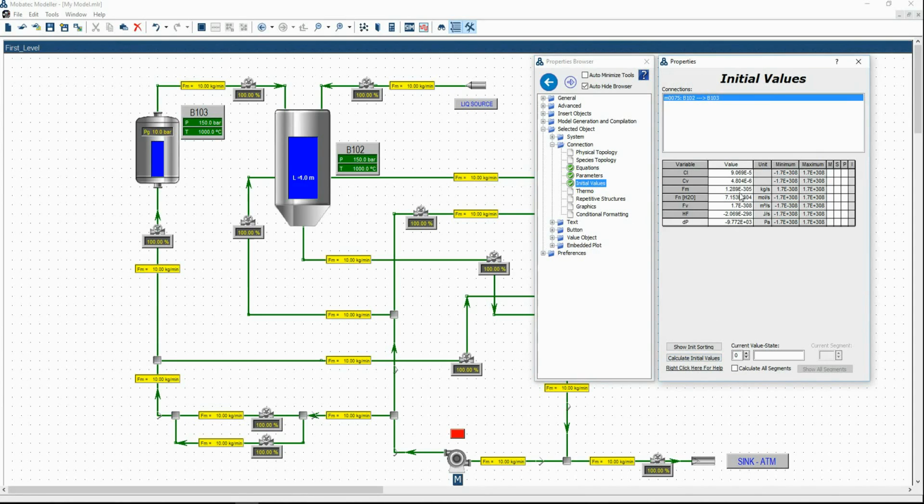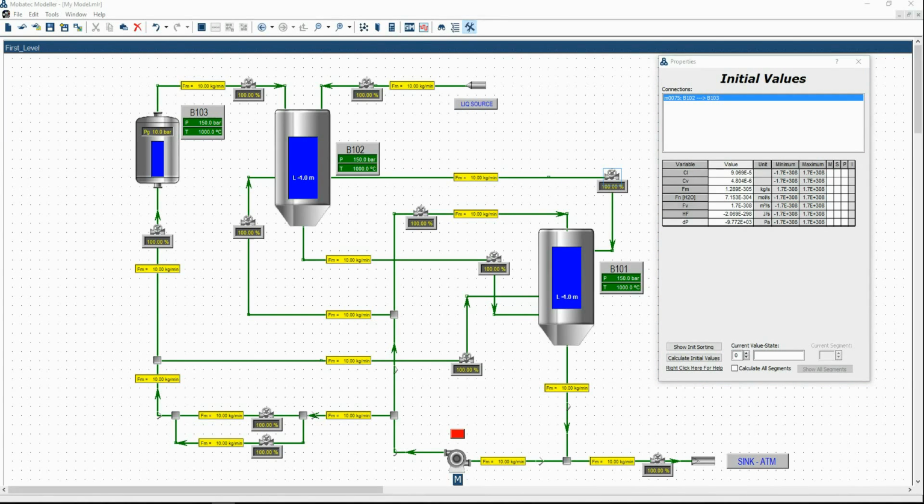Mass flow is 0, as if we go to parameters we will see that our ZV parameter, which is valve opening position, is 0. We change that to %. Because this is 0, we have 0 flow. For now we will leave it to be 0, and once we compile the model we will open the valves and play with the model. Use figure 9 to enter the correct elevations for each mass connection in the model and initialize each mass connection.